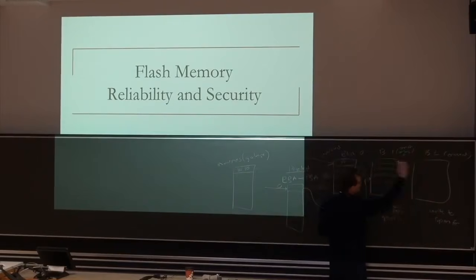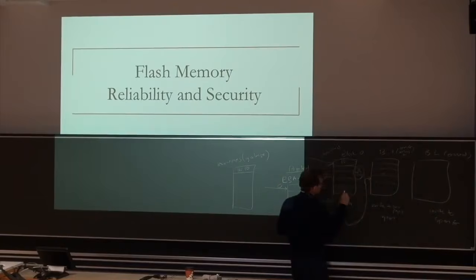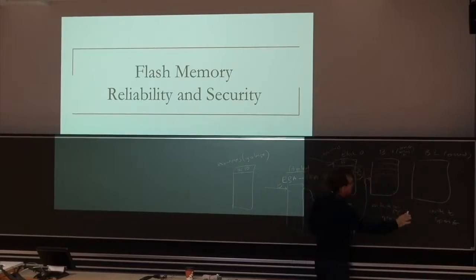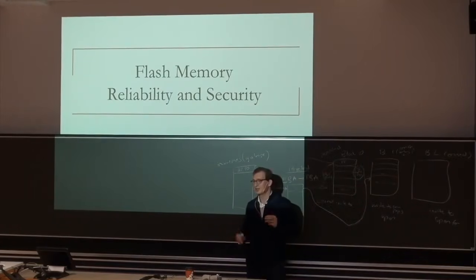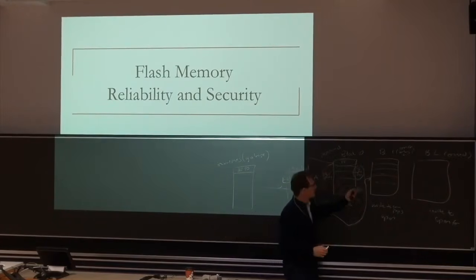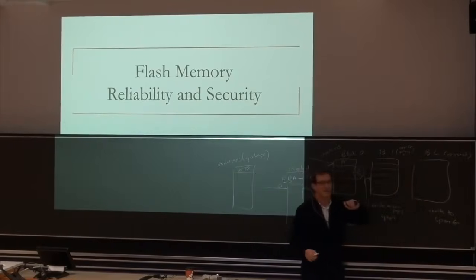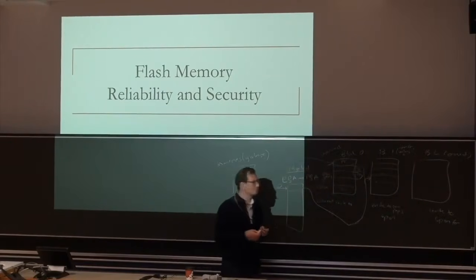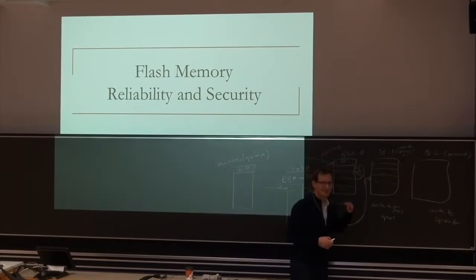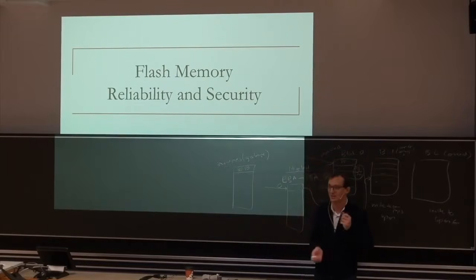Maybe it's better to level this wear or wear out across the blocks somehow, such that you level the number of writes across the blocks. The question is, how do you do that while also trying to minimize the garbage that you have? That's why the design of the controller is actually a very complex design, because these things actually go against each other.